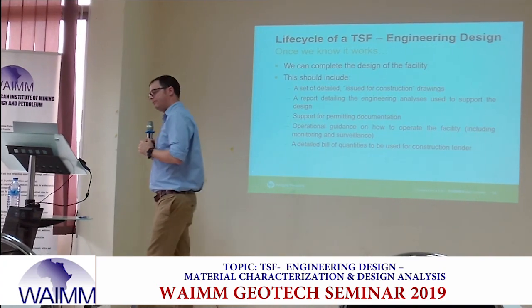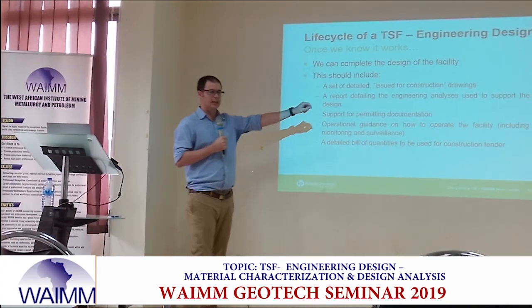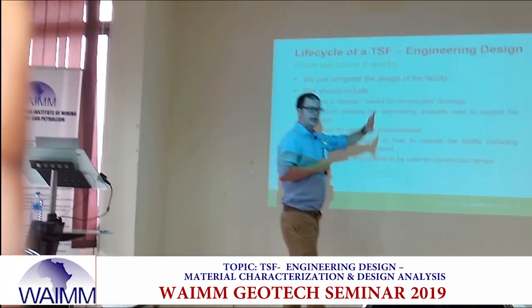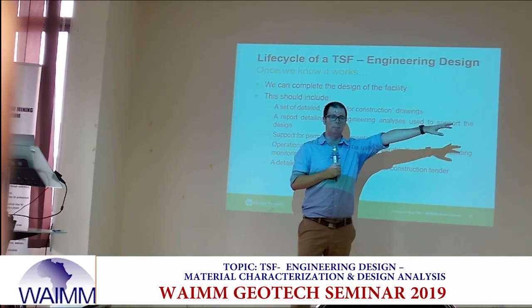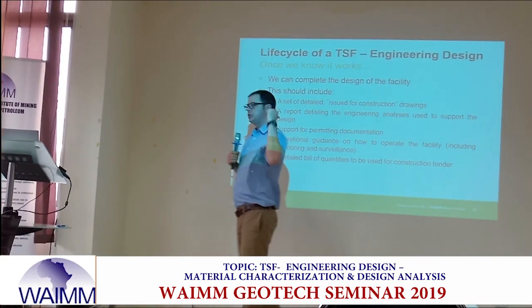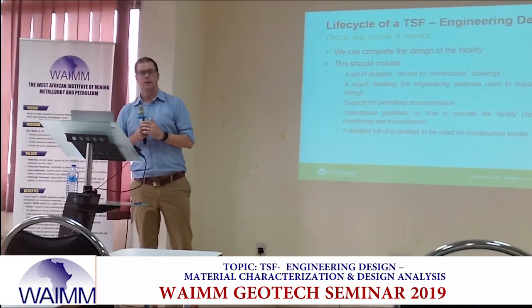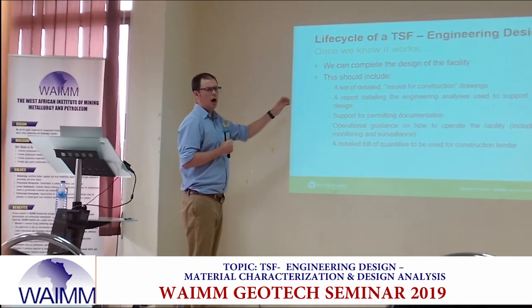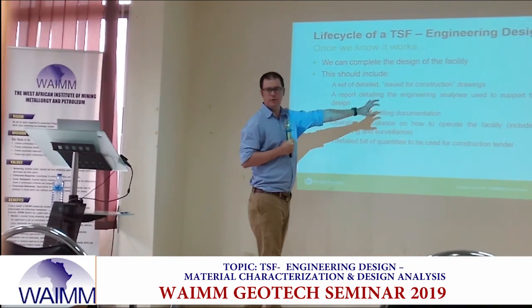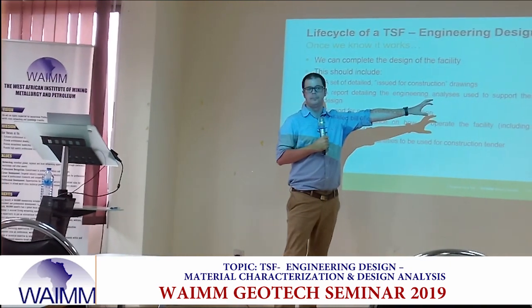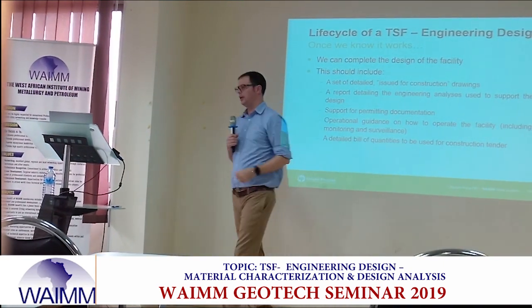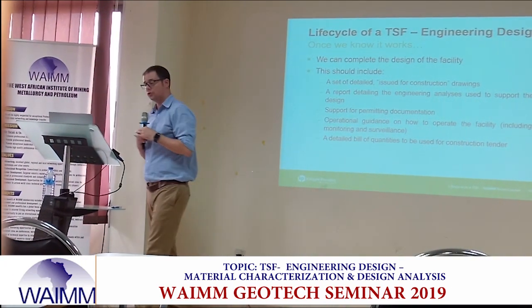Okay? If the design assumes that the tailings pond is far, far, far away from the embankment, that needs to go into the operations manual. Because if we don't have an operations manual, right, the operators might say, oh, this facility was designed with the pond against the dam. Those are two very, very different things, and the results can be catastrophic.